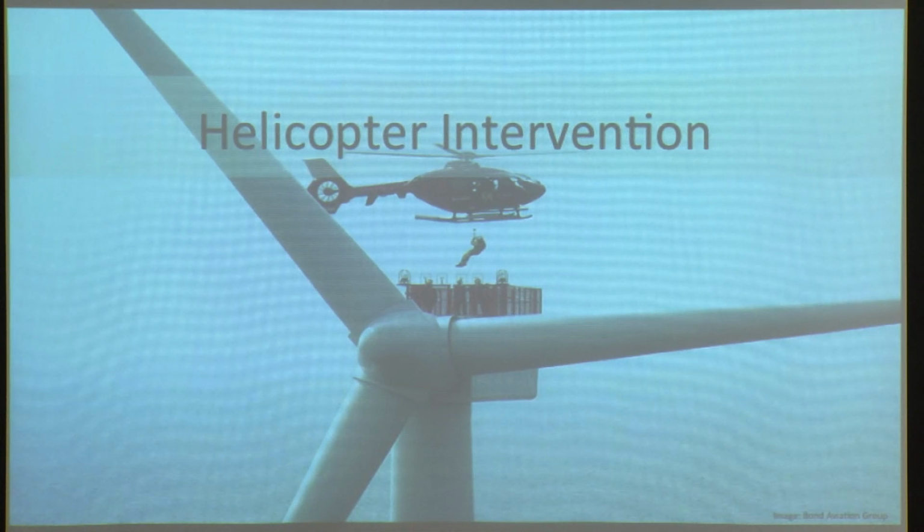Waves are very difficult, especially in the North Sea. There are periods that you just cannot access the turbine. So it can be weeks that you cannot access it due to the high waves. This means that if you have a component that is broken, we've seen this, it can take 3 months before it's replaced due to lead time and due to weather conditions.